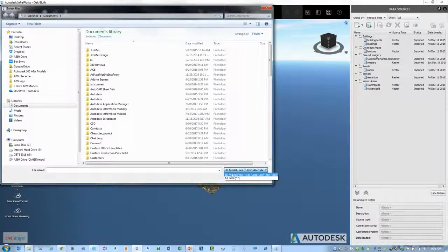Now, one of the things I particularly like is I love Navisworks. In Navisworks, I can aggregate or isolate things and then export out to FBX. That's one of the things I did a great deal of over time: whatever model I had, if it had a little component of something that I wanted or needed, I could isolate that thing, FBX it, and create my own object from it, kind of a duplicate.